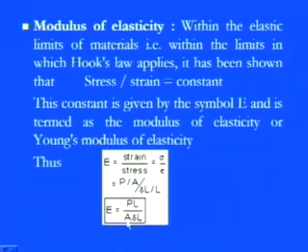So this is, we can say, the main property of the material, the limiting value. This is absolutely valid when we are talking about a ductile material. If a material has the ductility property, then it can be easily expanded. It does not show rupture or fracture when the load is applied, and for that it is pretty easy for us to define the elastic region and the plastic region.